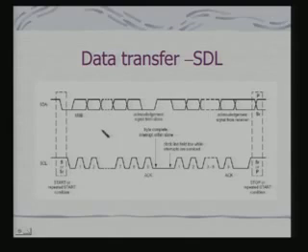So, now if we see the waveform, it is the same thing. What you are finding here is the acknowledgement which is coming. So, at this acknowledgement, the SDA line is now pulled low by the slave, and this corresponds to this clock pulse which is generated by the master.